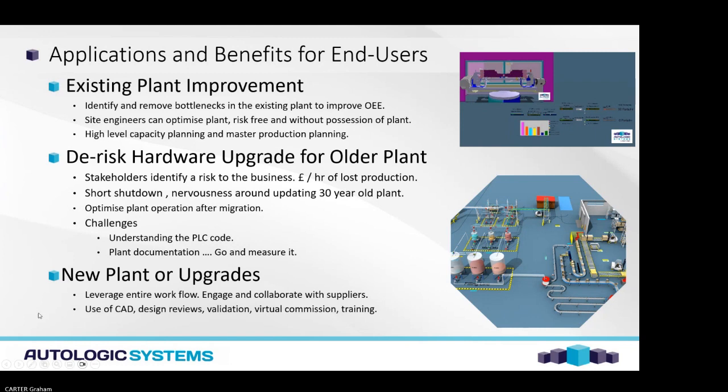There are some challenges around it. You've got to understand the PLC. It's very unlikely someone will know that software from 25, 30 years ago. The older plant might not be documented so well, and we often find ourselves going on site with our laser measure and a tachometer and start measuring time and distance to feed into the digital twin.